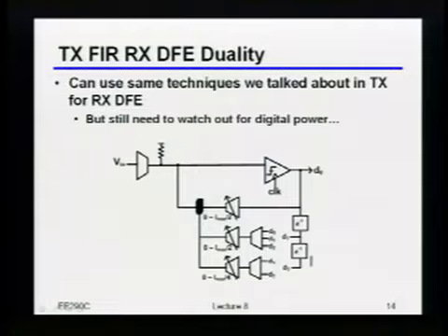And in the limit, you'd have a big digital signal processor here that would generate some number of bits, and then you'd feed it into a DAC, right? That would give the minimum parasitic capacitance you can get, but the maximum amount of digital power you could be spending. Yeah? So that also adds digital delay, right? That's right. This also shows up as delay in your feedback path. Now, there are some tricks you can play here, because, for example, notice that on this first tap, which tends to be the most critical, I didn't put any muxing.